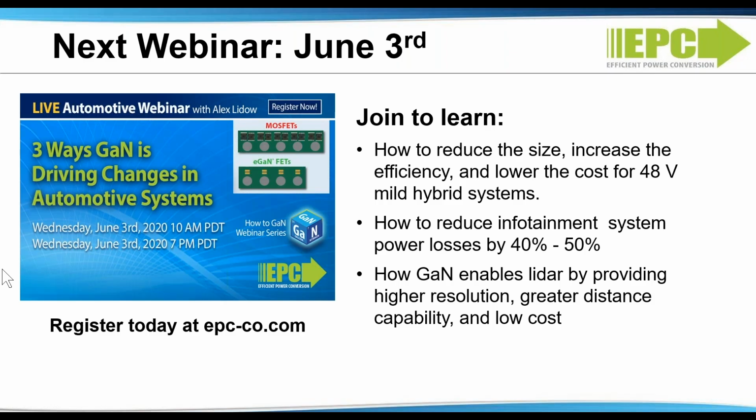A 300 watt 48 volt to 6 volt LLC was shown with both a half bridge with 2 primary FETs and a full bridge with 4 primary FETs. How can these designs both process the same amount of power? Well, the difference is in the transformer design. The half bridge version uses half the turns and thus will have much higher current, about twice the current, and will need larger FETs.